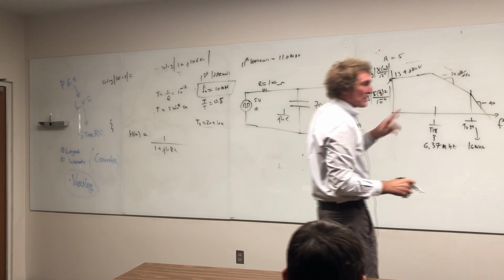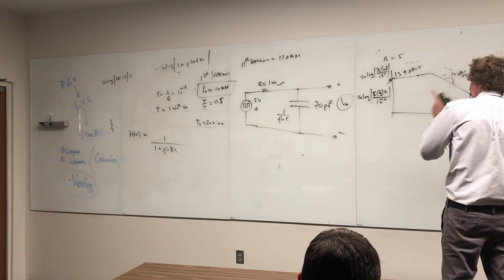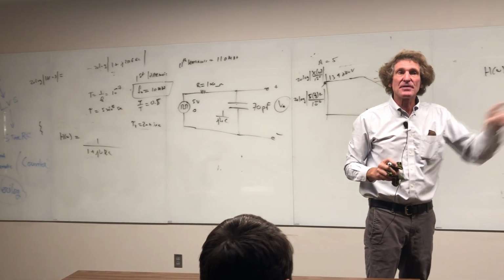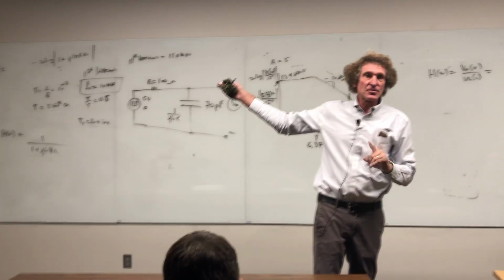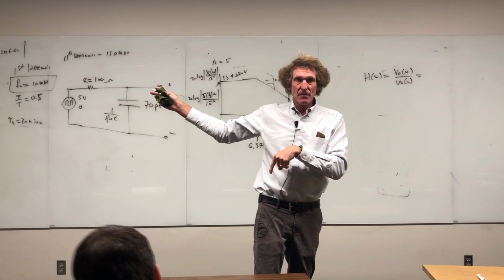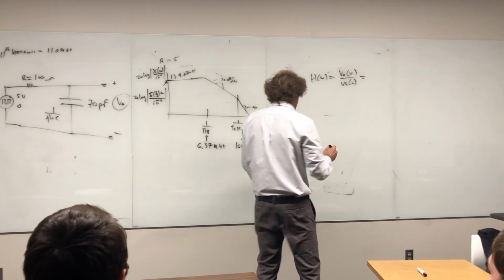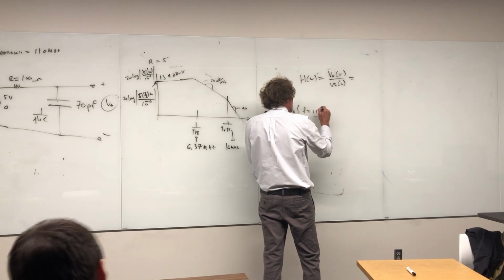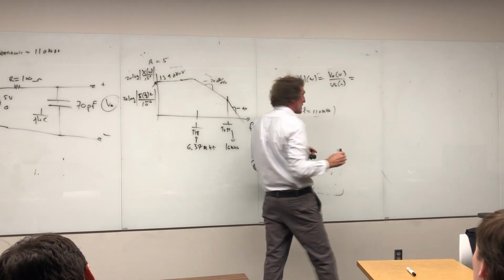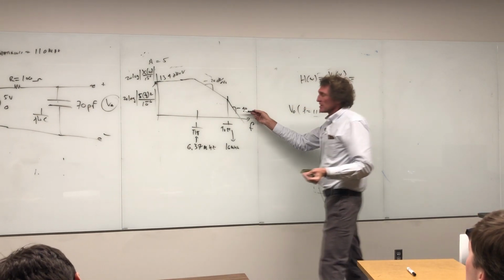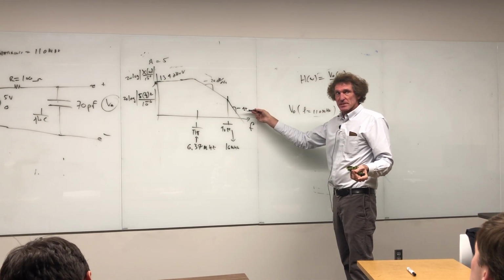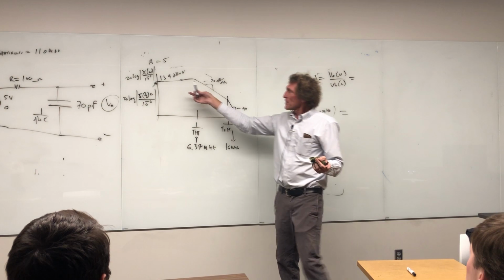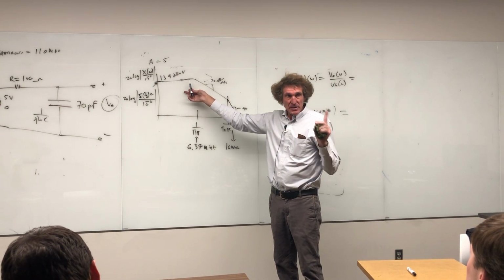So now I come down here, and when I actually look at my output, as before, I take my input signal here in dB microvolts, and I add to it 20 times the log of the filter at the frequency of interest. Follow me on this one. So I'm going to say V out of the 11th harmonic, or F equals 110 megahertz, in dB microvolts, is going to be the value of this at 110 megahertz, right? Now, please pay attention here. This is important. When I'm doing this, I know I've got 134 dB I'm starting at. Correct, class?